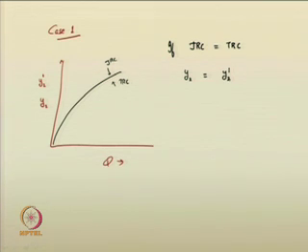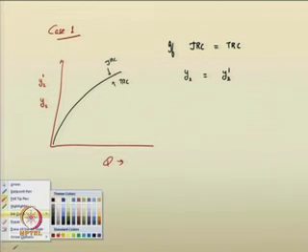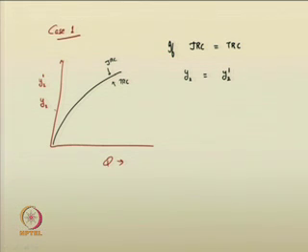That is the meaning. Irrespective of the situation, if I take this depth, then the corresponding discharge is here. If I take another discharge q 2, its corresponding depth will follow the same sequence, that is, the sequence depth as well as the tailwater depth will be the same.